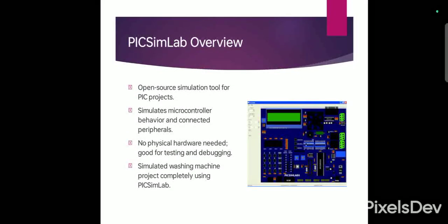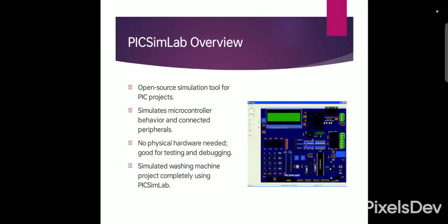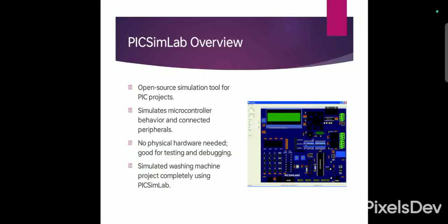Next one is PICSimLab overview. The PICSimLab tool is an open source simulation platform that supports PIC microcontrollers. It lets us simulate circuits and peripherals without any physical hardware. I used it to test the washing machine program and simulate switches, fans, and buzzers. This was very helpful to verify my design logic.